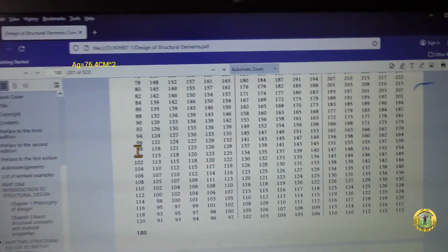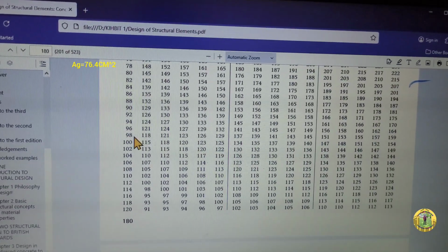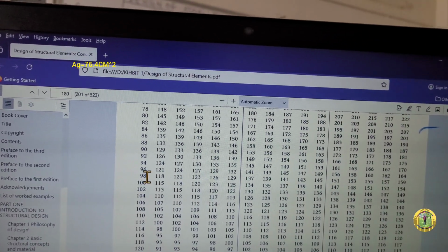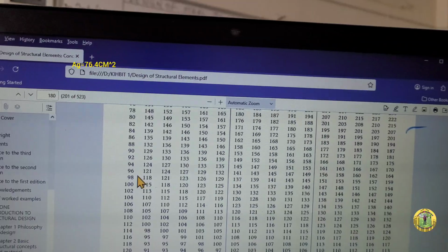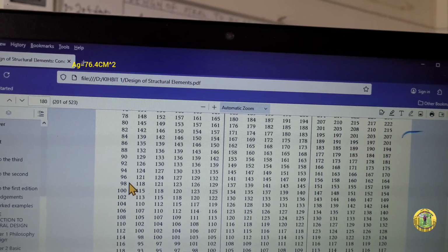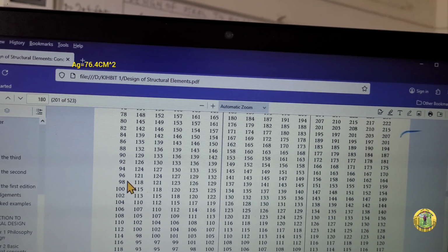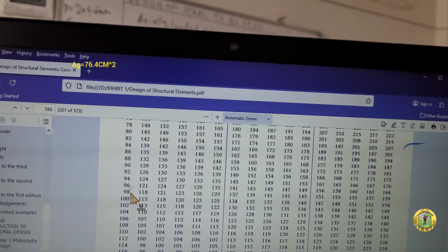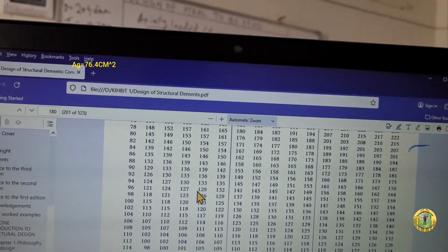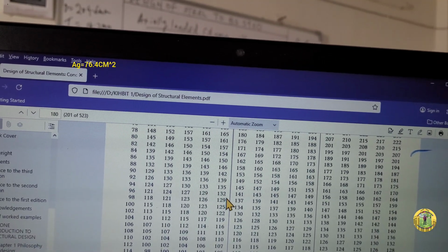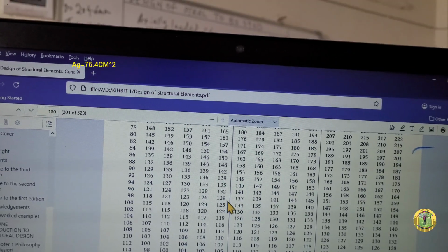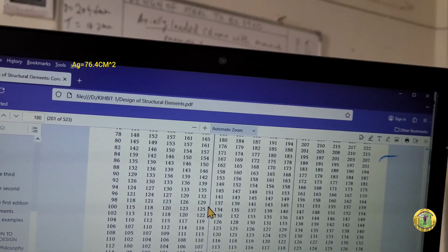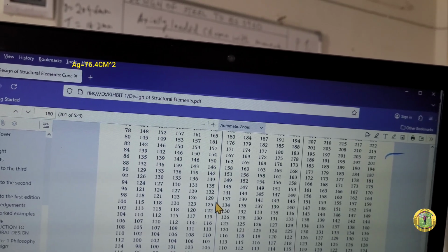As you can see, we have 98 and there is no 98.02. So we'll interpolate. You take a value slightly lower than 98.02, which is 98, and the one slightly higher, which is 100. And for 98, we'll go up to where 275 is. This is the last column. We have 129, and for 100 it is 125. And then you do the interpolation to obtain a PC for 98.02, as shown on the board.